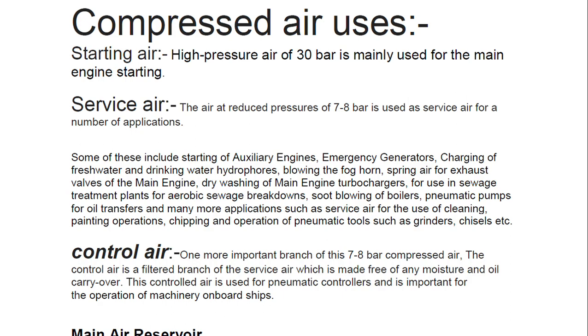You see, in the first stage only we are injecting the air. Also soot blowing of boilers, pneumatic pumps for oil transfer, and many more applications such as service air for cleaning, painting operations, and chipping. We are also doing chipping with pneumatic tools such as grinders, chisels, etc. So for all these purposes we use this 7 to 8 bar air.